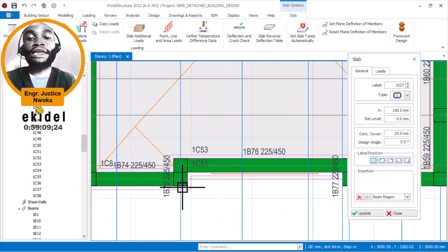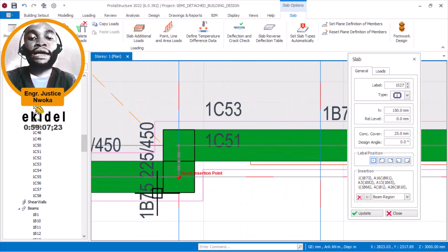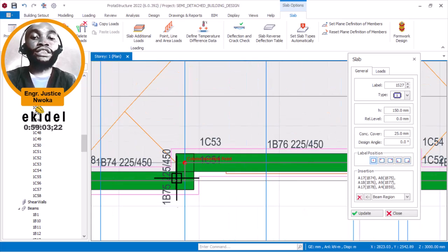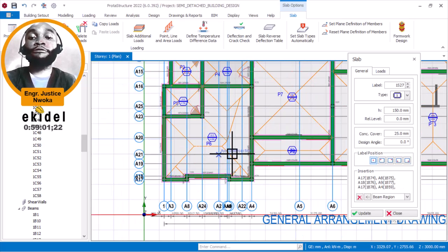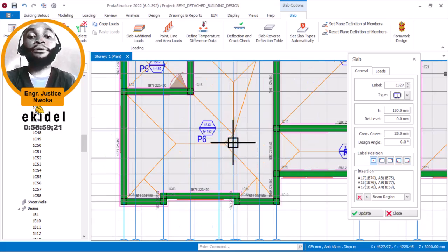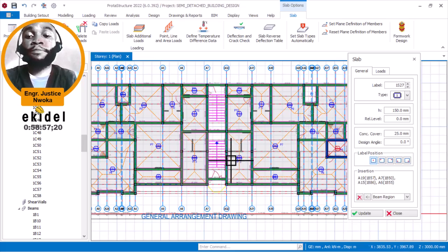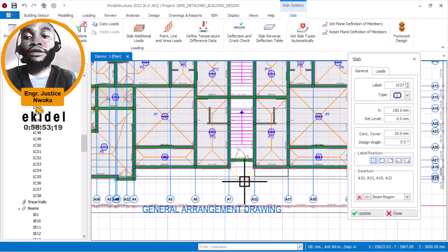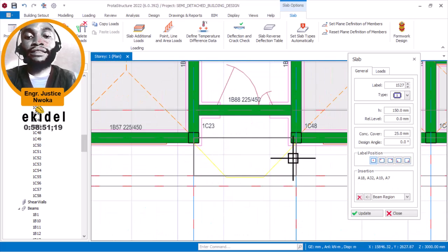So divide the columns into 2 like this, and then make a small bend to pass through that place. During your detailing, you can choose to merge it together, okay. That's just to get your slab in this panel. That's fine. So with this, let's now go ahead and model our cantilever slab here.